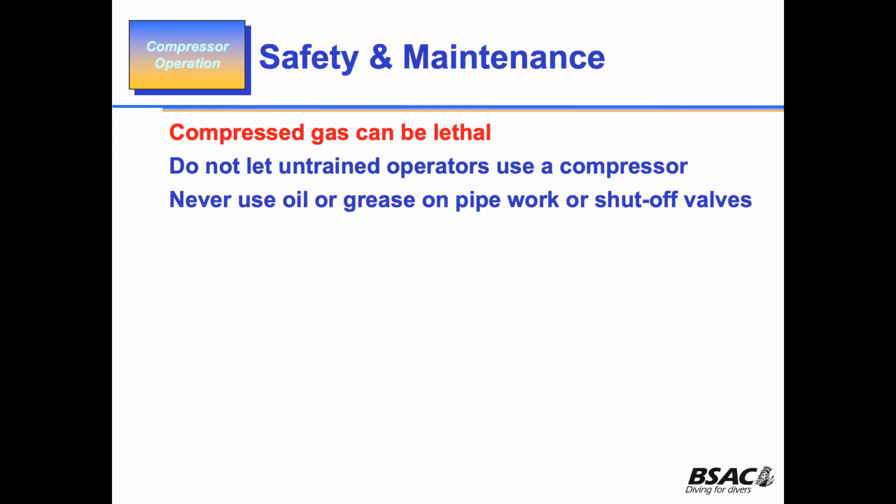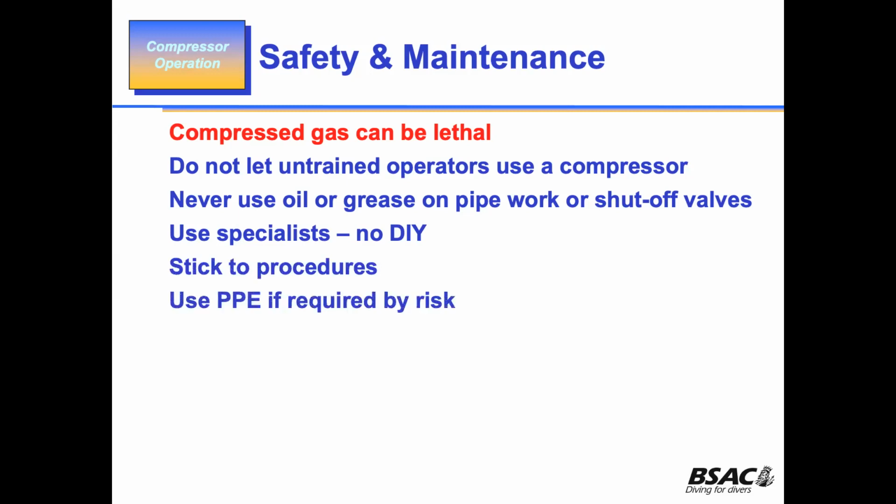Never use oil and grease on pipe work or shut off valves, right? Please don't. If you've got a problem and you don't understand that problem, get somebody in. Don't try doing it yourself. If you've got people who can do it, all well and good. But if you haven't, send it away or get somebody to come in and look at it. Stick to the procedures. Don't bypass. Use PPE like earmuffs and glasses, if it's required.